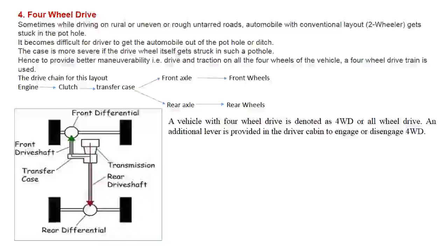In this case, our intention is that the drive is to be given to all four wheels, no matter whether the engine is near the front or near the rear. So to give the drive at the front as well as at the rear in this four-wheel drive vehicle, the transfer case is used. For four-wheel drive vehicles, the transfer case is particularly used. At the same time there are two differentials, at the front for the front wheels and at the rear for the rear wheels.